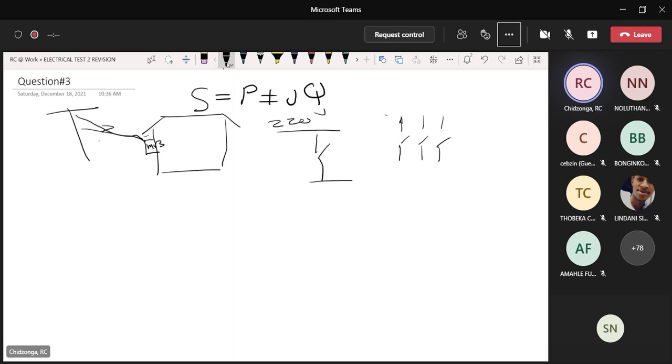So here you've got a bus bar. If you check inside the panel, the box where the electricity comes to, all these points connect to a particular bus bar, and that bus bar is connected to this main incomer. So this is your main. If this is 220 volts, everywhere here is 220 volts. The switch here might be going to lights, this one to the washing machine, this one to the geyser. In other words, all these things are in parallel.